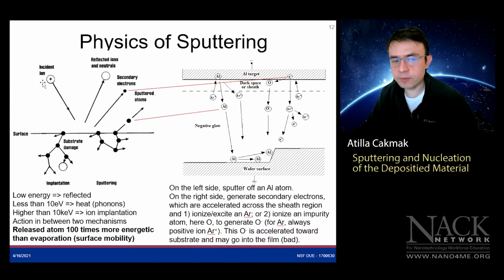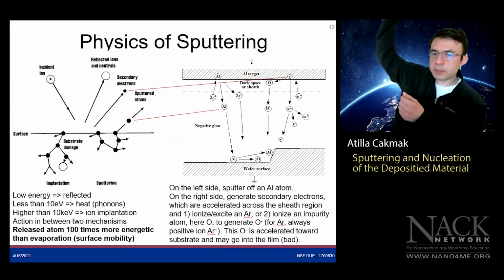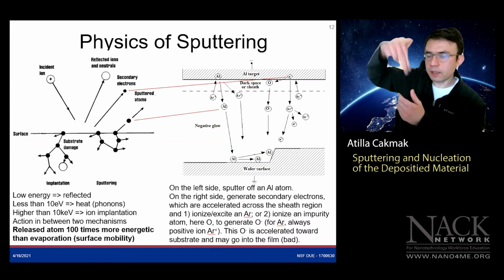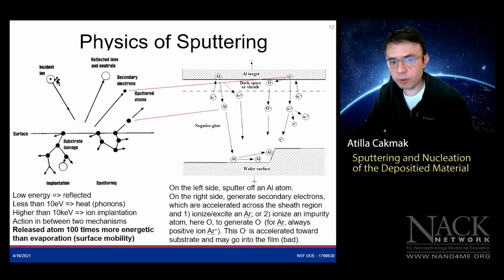We're going to attack the surface. We talked about the plasma generation and how we can use that roller coaster effect, the sudden voltage drop, with the incoming ion. We're going to use that ion, speeding it up, to attack the target and knock off more electrons for secondary ionization, which is our main source of electrons, but also to knock off other particles from the surface. That's going to be our main deposition particle too. Those are our two aims, but we might have implantation and other things coming into play too. We're going to see that in a bit.